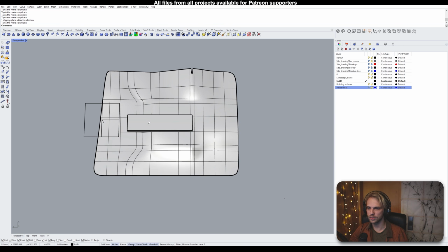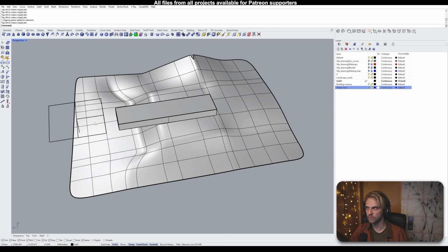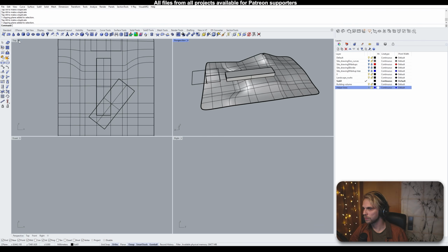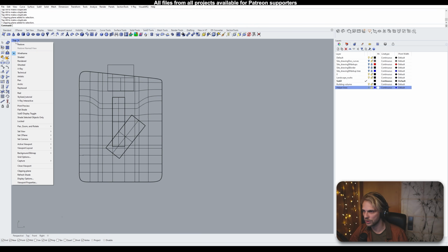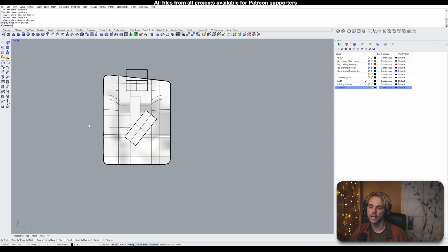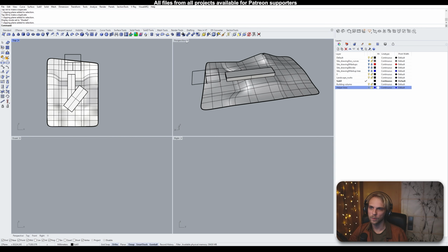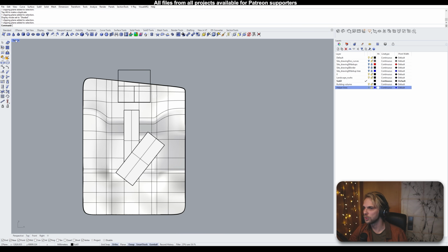So for me to get the section plane of the first plan, all I need to do is position it at the correct height, then go to the top view and change this to shaded view. While in the top view, I notice that it's not cutting my geometry here. While in perspective view, the clipping plane is indeed cutting the geometry. In the top view, it's not.